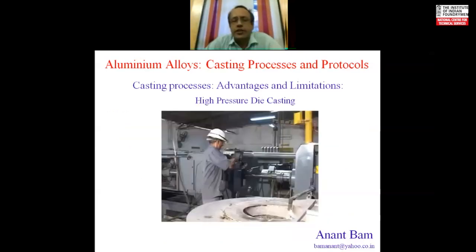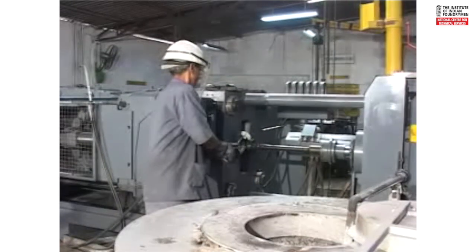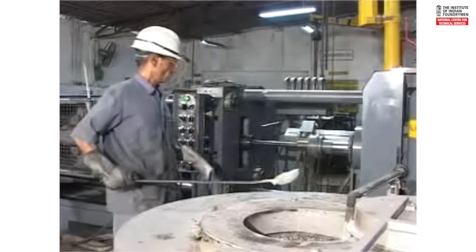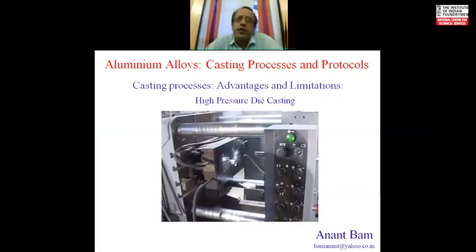Pressure die casting. Herein, you can push the aluminum metal just like injection molding. Metal is poured into the cylinder, a piston pushes it, the metal is filled into the die, and after solidification, it is ejected. In case of pressure die casting, metal is injected into a pressure tight die by pneumatic force very rapidly. Since the pressure is very high, equally strong clamping force is needed.